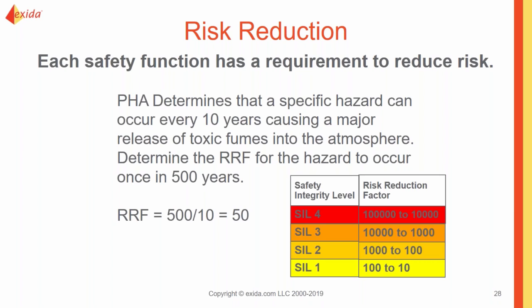But if you've done all of your PHAs or HAZOP, you've determined you still need to remove risk, that's when we incorporate that SIL. So each SIL level is going to be 1 order of magnitude. Once again, that SIL 1 being taking out the least amount of risk. SIL 2, an order of magnitude up, it takes out more risk. SIL 3 takes out even more risk. And SIL 4, well, we know that that's kind of that impossible or very rare case scenario.